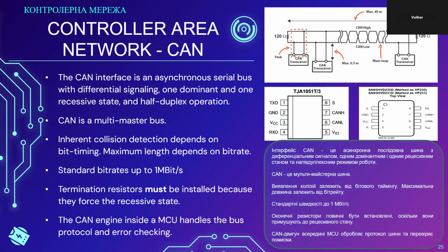But one has to be aware of the limitations. And one of the limitations is it can be fairly power hungry, in terms of 50 milliamps, which was not a problem for the situations that the CAN bus was designed for. The CAN bus was designed for an automotive environment. And in an automotive environment, 40 or 50 milliamps are absolutely not a problem.